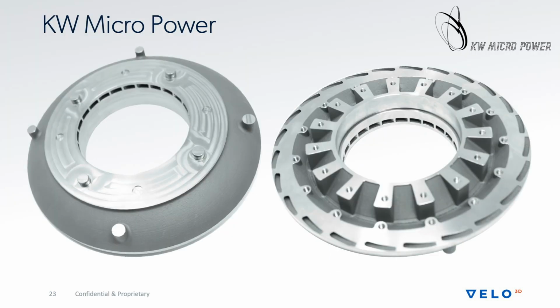To use this in a real example, I'm showing a part from a company called KW Micropower. This is a turbine diffuser. It's about 10 inches in diameter. It's a titanium part, and they were bidding this part out to a number of manufacturers and getting no bids from almost everybody. The reason being mostly, as a sidebar, it's very difficult to print large titanium parts without cracking because of the brittleness of the printed titanium. Impeller has a proprietary process to mitigate some of that and print large parts like this.